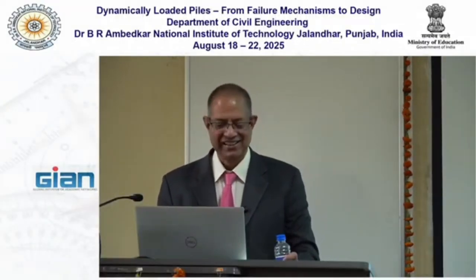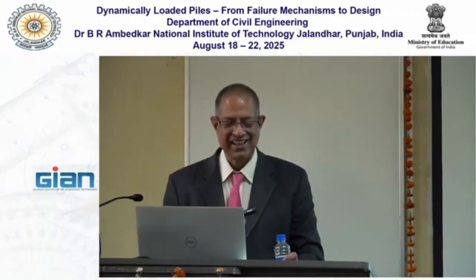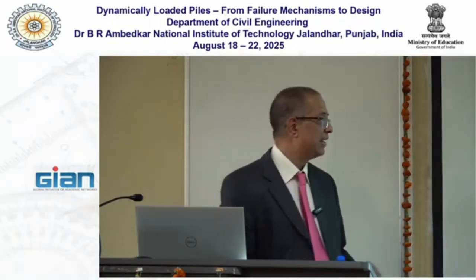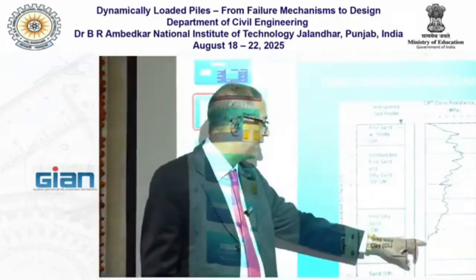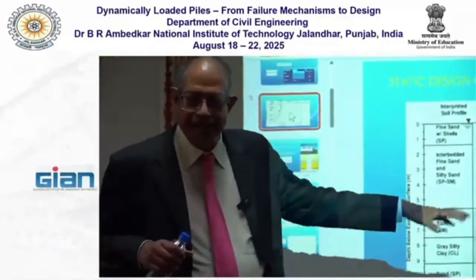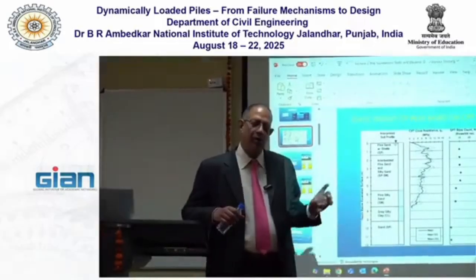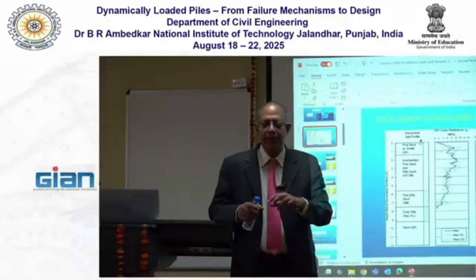Yeah, yeah. Normally in end bearing estimation there is CPT, there is an averaging of 2 diameters up and down. Yeah, why was it not done? You could do it. I mean, here you can see this is coming quite low, so whether you average it up and down, it's not going to make a difference. There are many variations of applying the CPT. I'm not arguing one is right or not. Also, with the CPT at very shallow depth, the failure mechanism doesn't fully form. Therefore, it is also there.